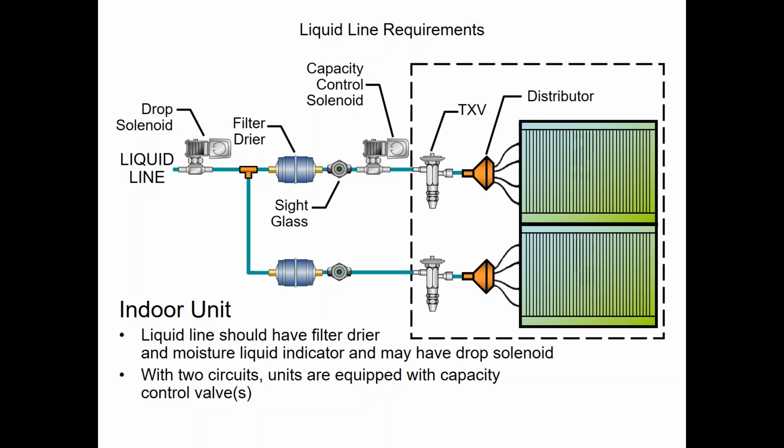So understand weigh-in charge. It's the way to go, and that's how it's calculated. Again, you don't calculate for your suction line, you don't calculate for your discharge line. You calculate for the liquid line, the evaporator coil, and what the condensing unit or chiller's operating charge is for 25 feet. Add it all together, and that's your best starting point.